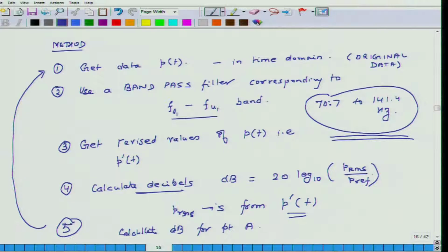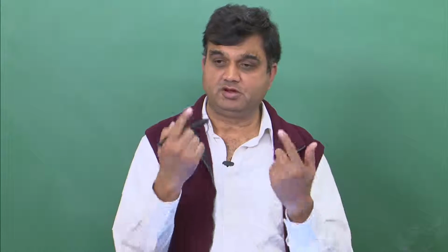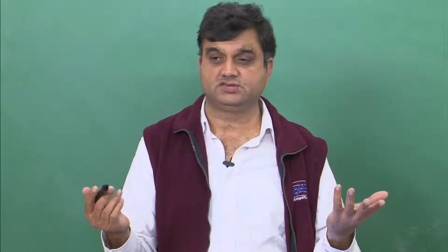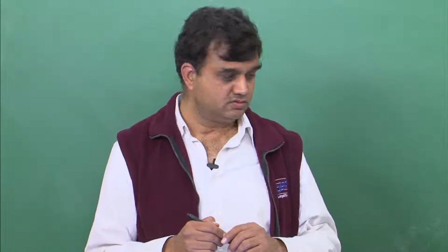So when you do this octave analysis, you don't have a phase plot and a magnitude plot. You only get the energy, which is magnitude, right? You cannot calculate phase, because all frequencies are clubbed into one single number. So there is no such thing as phase. It's irrelevant. So this is what you do.